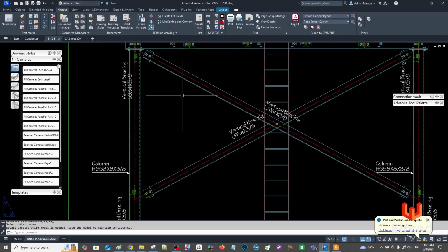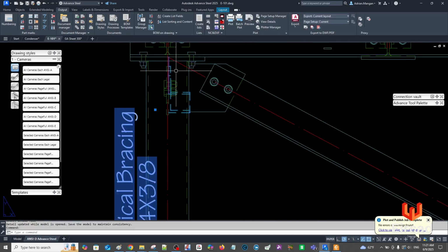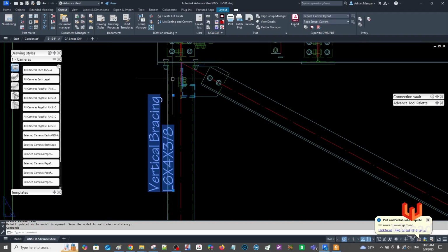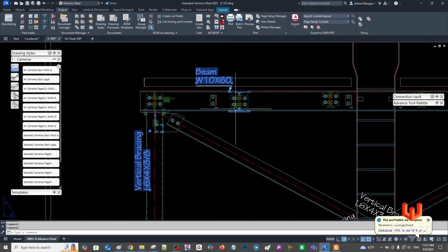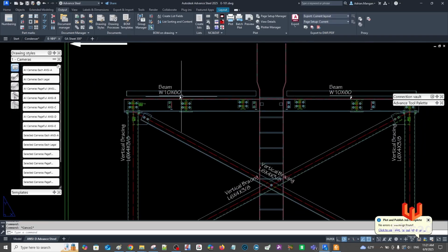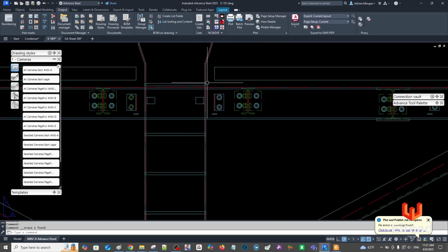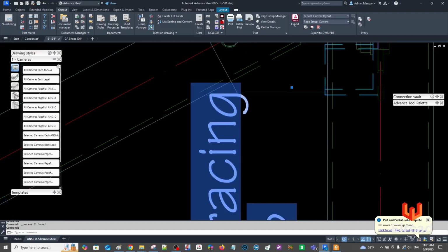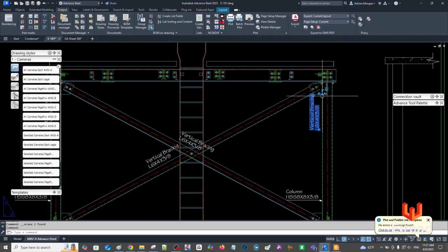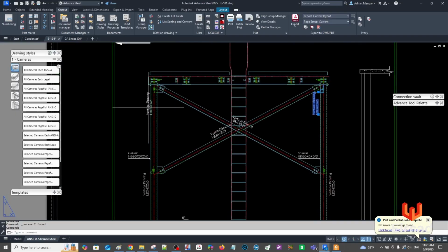Right, so you can see now it has also brought in these ones over here, which I don't want to have in. You can see it's bringing in this beam here. The reason it's bringing in this beam is because it can see the bottom of the beam. So these are going to be available in the plan. If it's not going to give you all of them, maybe it's as well off to just delete them ones and just give the measurements between them. This vertical brace, see the way it's seeing the corner of it, that's why it's giving you that one. I also would delete those.